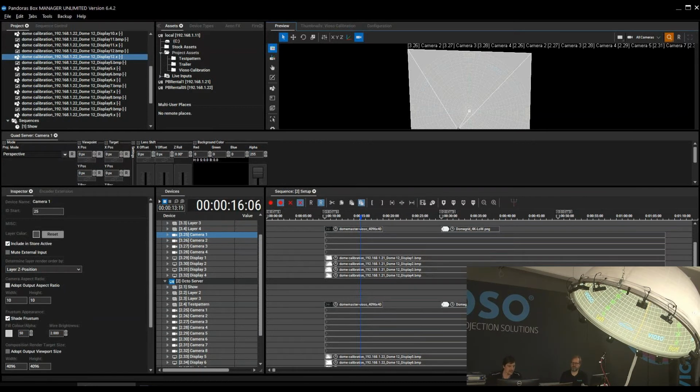So I uncheck this checkbox because the output aspect is 16:9, I think, 1200 by 800. 16 by 10? Okay, 16:10. I'm not using that because my original texture is a 1:1 aspect. That's the first thing, to make the camera able to have a different aspect than the output.